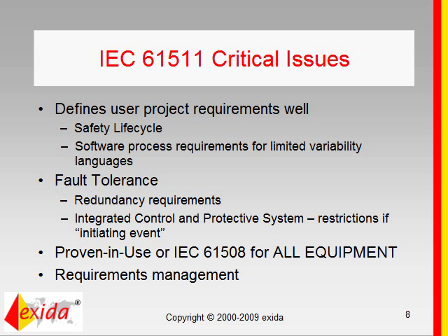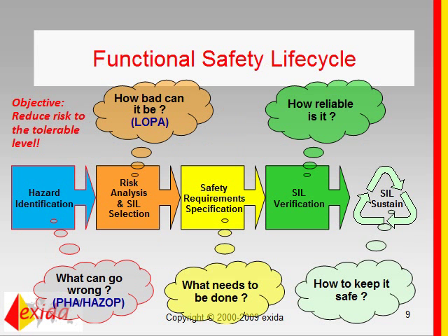So those are some things that arguably are all part of functional safety management, and good functional safety management has a well-defined life cycle approach for implementation of 61511, but that could be a little bit tricky when you start out with this stuff. As an idea of what this functional safety life cycle looks like, we basically start at the beginning when we have a concept.